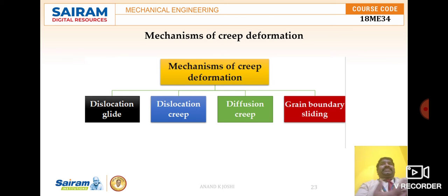This takes place at higher temperatures, where atoms vibrate rapidly, permitting the dislocations to climb to another plane, thereby relieving the stress pile-up and permitting them to continue their motion. This is a response to the applied stress, and it results in plastic deformation of the material.